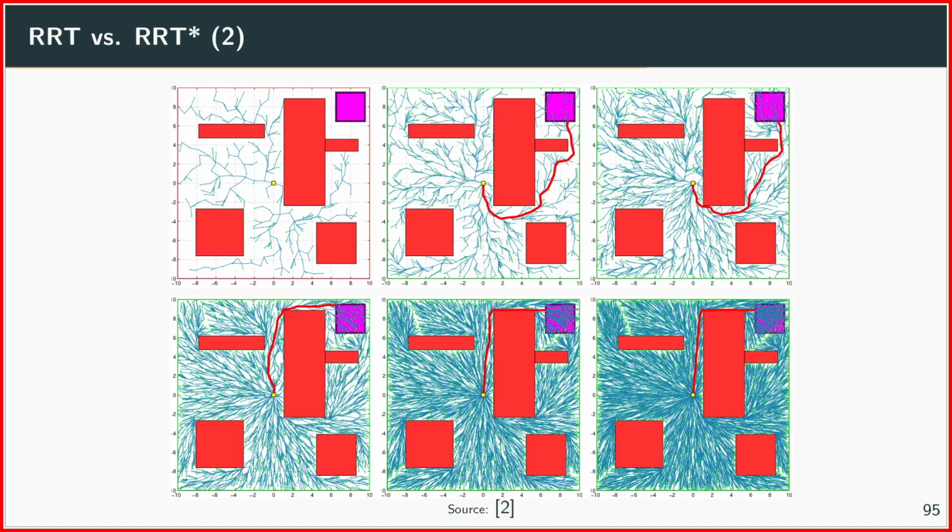As you can see here in 2D, the first time we find a solution, we already have a very big tree, and then if you have to go over all the nodes and all the edges again and do this optimality rewiring, it might be a bit costly. And if it's already costly here, then in 10, 20 dimensions it might take another hour or so. So it might actually be more efficient to do it in every iteration to always keep the optimality. Okay, basic version, any other questions?